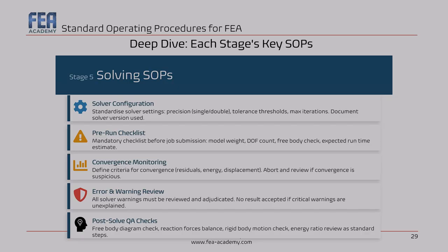The solving stage is where most engineers stop paying attention. And you see what I mean there. And it's where some of the most damaging silent failures occur. The solver runs overnight. You come in the morning and you see "solution complete," and you go straight to the post-processing. That is not an acceptable workflow.